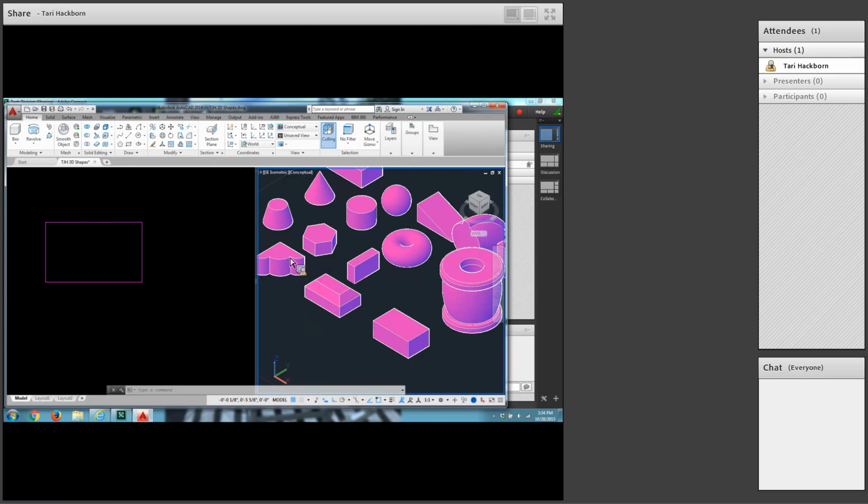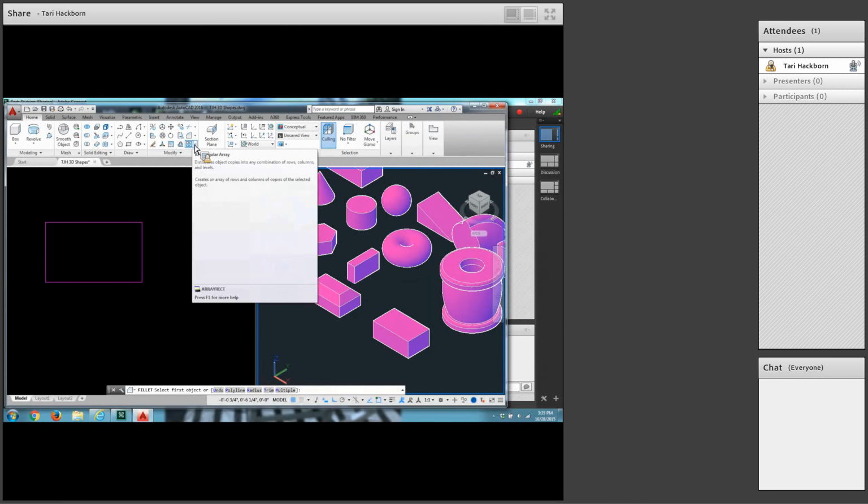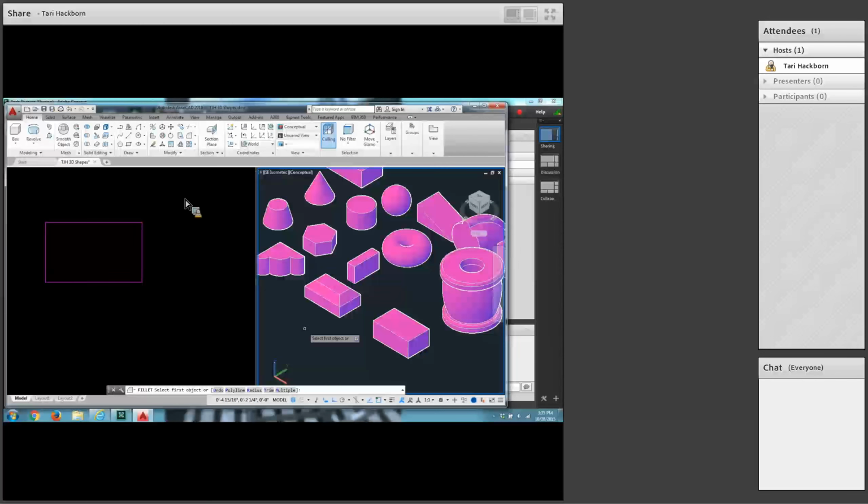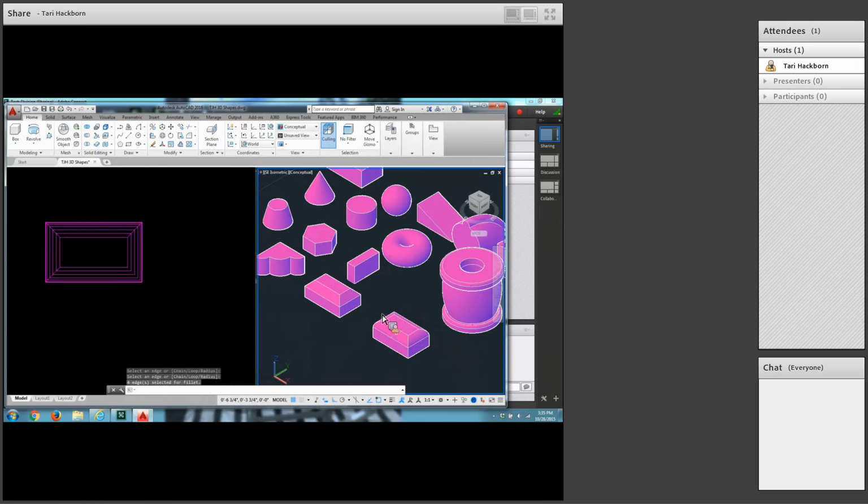Okay, select fillet. Okay. Select P5. Well, then I got to turn back a page and see which edge was P5. Okay, this one back here. Okay, select P5. Okay, then it's calling for the radius, 3/16, and enter. And then pick the other three edges. Okay, was there any special order they wanted them in? 6 is here. 6, 7, 8, and enter. Okay, works a lot nicer than the chamfer.